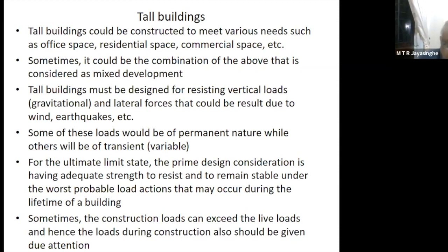So you have to always keep in mind, when you are dealing with large structures, never ever design based only on codes. You must have your own rules. And one of the rules is, always look at the member you are designing and see the location where it can fail. Ensure you have some extra factor of safety.